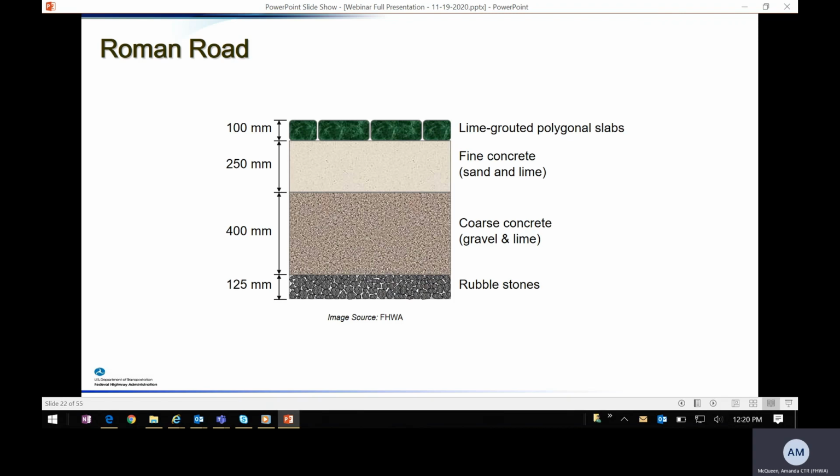They have various different layers, and they have about 3 foot of material for these roads. And these cross sections are pretty similar to what Europeans are building today. The only difference is maybe a couple inches of total thickness. So this middle layer is kind of like a stabilized layer, lime stabilized. So what they built is kind of like an inverted pavement. But the key point is they paid attention, and this wasn't done by accident.